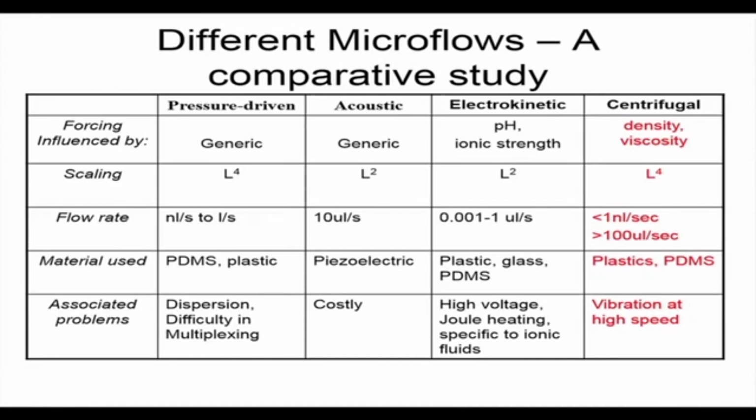But we have to keep in mind that when we are talking about the rotationally actuated microfluidic platform, the channel may be of small size, but the rotational force may be strong enough so that inertial effects may be important. So we may not always trivially neglect inertial effects, just as we commonly do in low Reynolds number hydrodynamics.